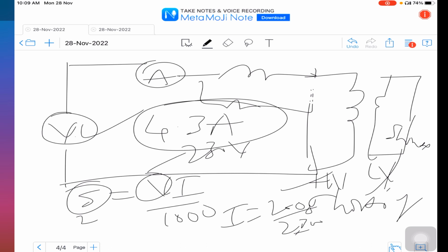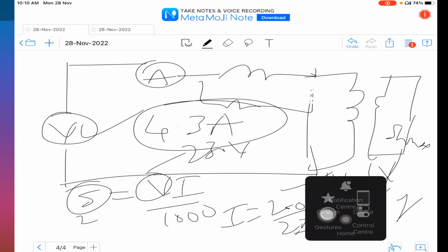So this is the rated current. The rated current is applied to the circuit, and we get a very low voltage and the wattmeter reading, which is at unity power factor. Once we get the values, we can find Wsc, Rsc, and V2, I2, cos phi 2. Similarly, as we did for the OC test, the parameters with respect to the secondary will be known to us. So this is with respect to your OC and SC tests.